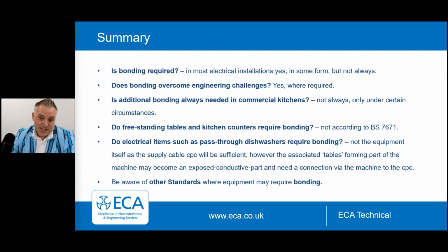So really, in summary, and this is sort of a quick tour of bonding, is it required? In most installations, yes it is, but not always. Does it overcome engineering challenges? Yes, and when we talk about extending your disconnection times, or where your disconnection times can't be met, the supplementary bonding is really useful in that situation. Is additional bonding always needed in commercial kitchens? Well, not always, only in certain circumstances, as we've discussed.